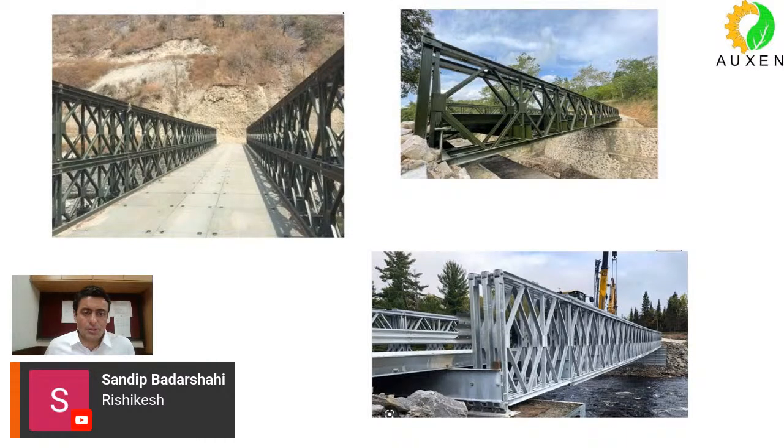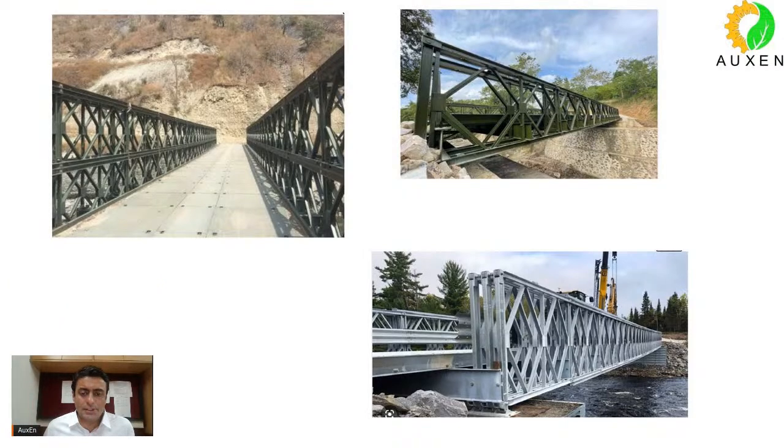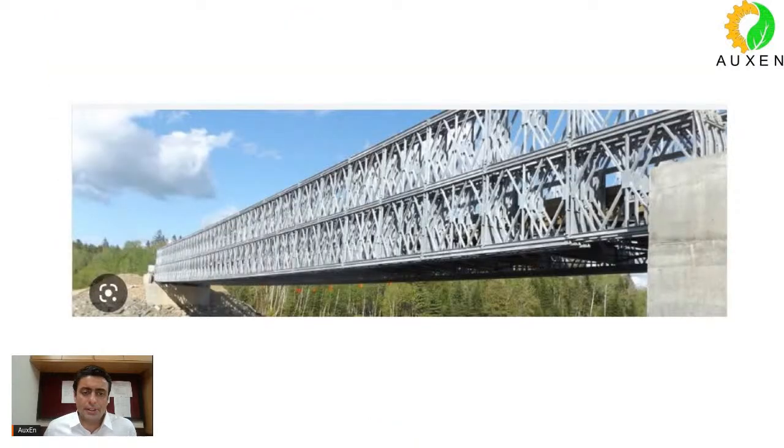Yes, so when I have shown you the pictures, you can recollect having seen these. If you see this third image, you will notice that the two Baileys have been stacked adjacent to each other. So with Bailey, you have this flexibility. You can stack them adjacent to each other, and you can stack them one over the other. All right. So this is the advantage that you get with this modular system, and they are quite often seen in the northern and the northeastern parts of India.